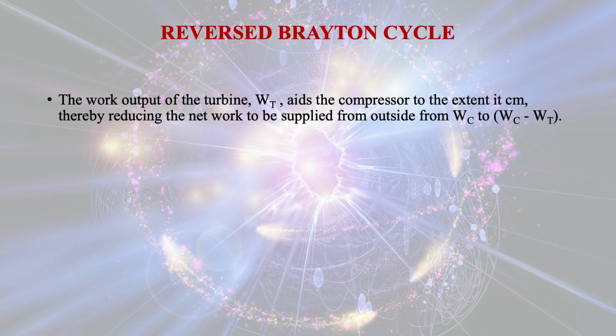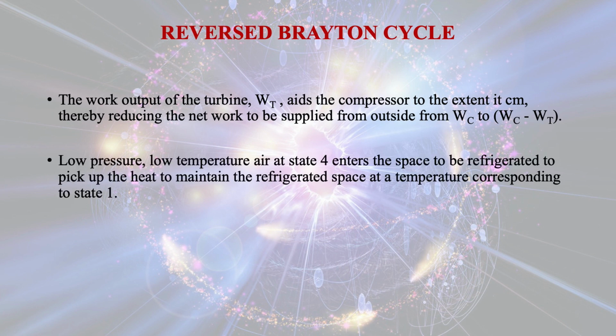The work output of the turbine WT aids the compression to the extent it can, thereby reducing the net work to be supplied from outside from WC to WC minus WT. Low pressure, low temperature air at state 4 enters the space to be refrigerated to pick up the heat to maintain the refrigerated space at a temperature corresponding to state 1.